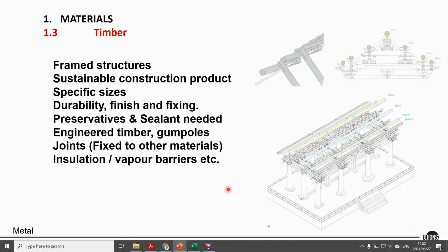Last thing before we continue to the next slide, if you're building a timber structure, remember you have to use insulation. Timber is not as insulative. It has some mass to it in terms of it gives you fire proofing, because if you use thick, big, massive timber sections, there's a limit to how deep it can actually burn, and the burning layer itself gives some protection.